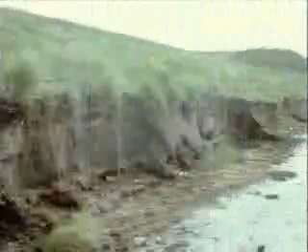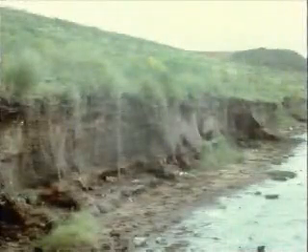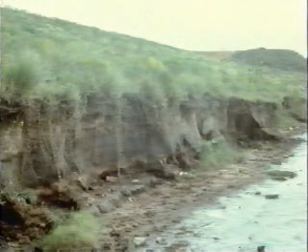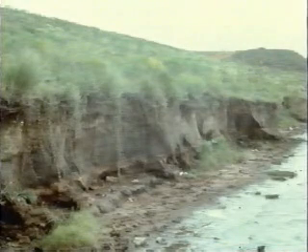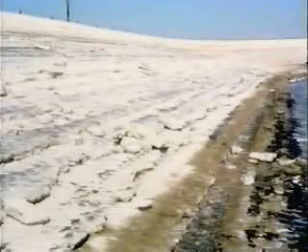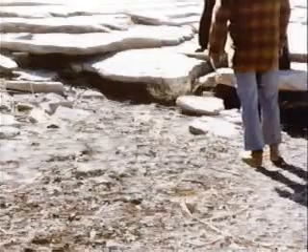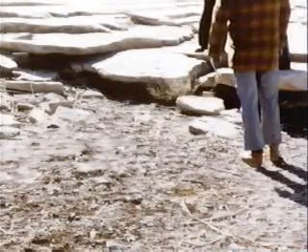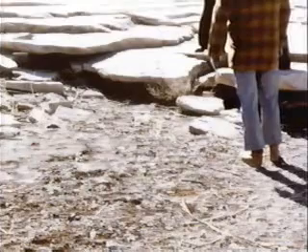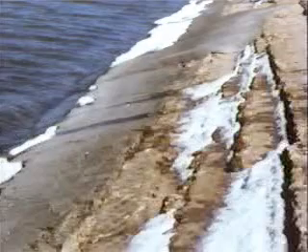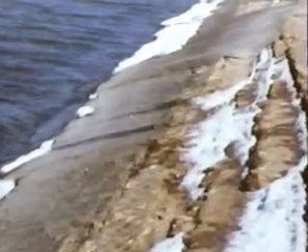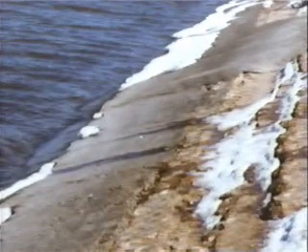Beaching can also occur on a grass-covered slope. When this happens, it's because grass as slope protection isn't effective at the site given the severity of wave action. Other slope protection should be considered. Finally, we showed you earlier what properly functioning soil cement looks like. Soil cement can also erode due to wave action. Only when a large portion of the soil cement layer has been removed and the dam embankment itself is threatened, should you recommend that soil cement be patched or replaced.